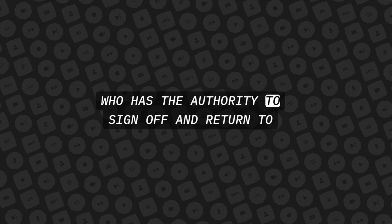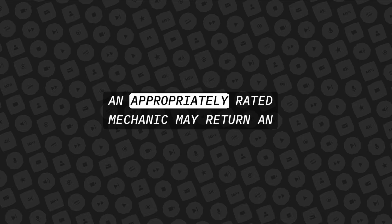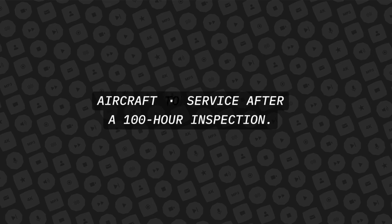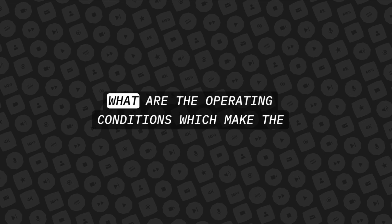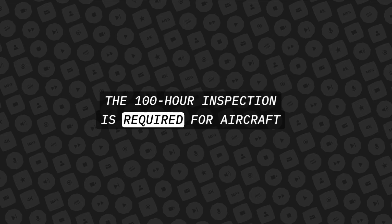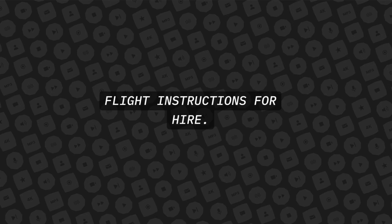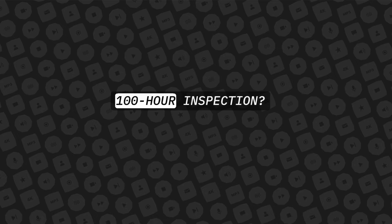Who has the authority to sign off and return to service a 100-hour inspection? An appropriately rated mechanic may return an aircraft to service after a 100-hour inspection. What are the operating conditions which make the 100-hour inspection mandatory? The 100-hour inspection is required for aircraft that carry persons for hire or is used to give flight instructions for hire. Where can you find a checklist for the 100-hour inspection?